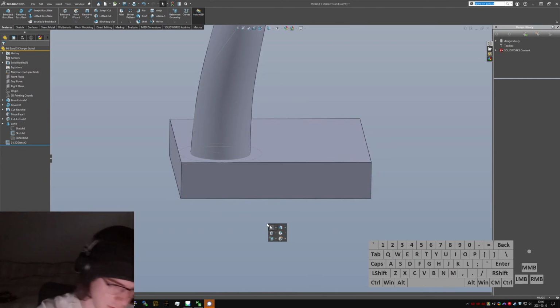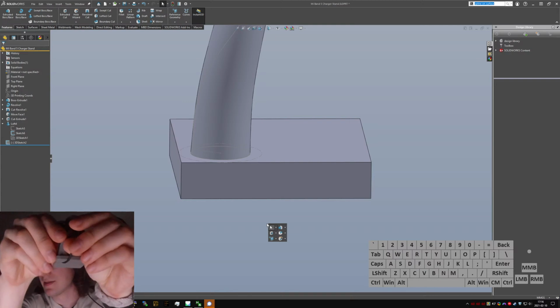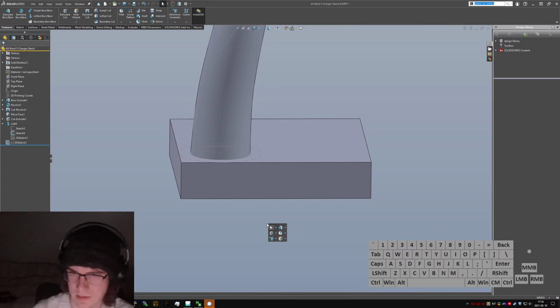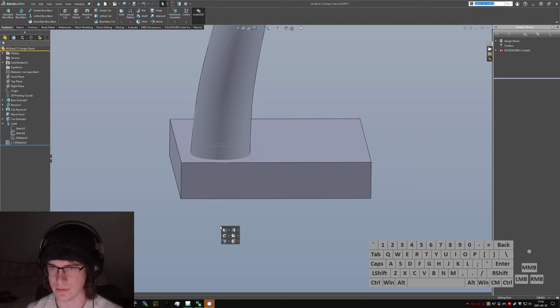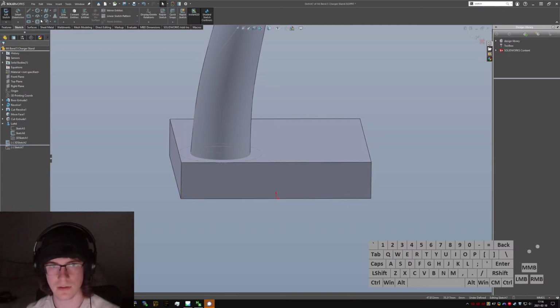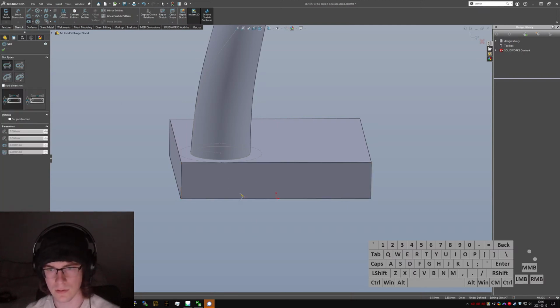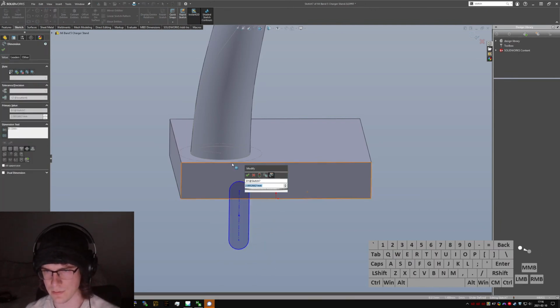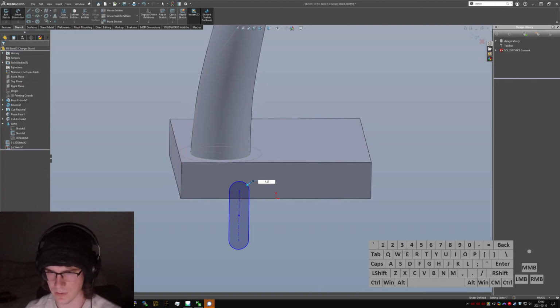So, one of the features on the original, I had this kind of exit cavity on the back, which means I need to replicate that. So we'll do just a quick sketch on the back side. Radius, that's not a radius, I want that to be, well, it wants to be 1.2 radius, but I want to dimension it as a diameter.